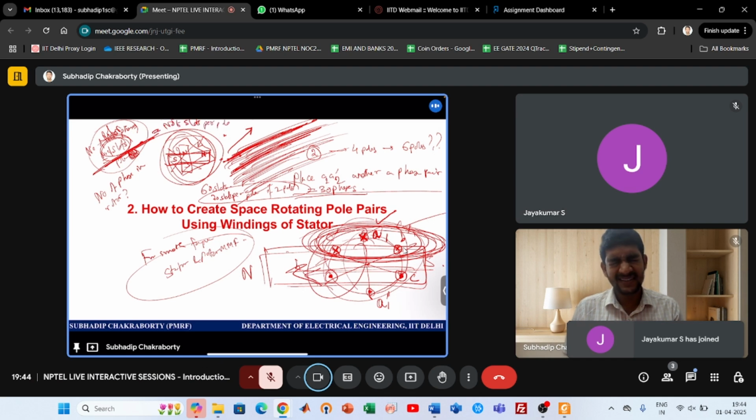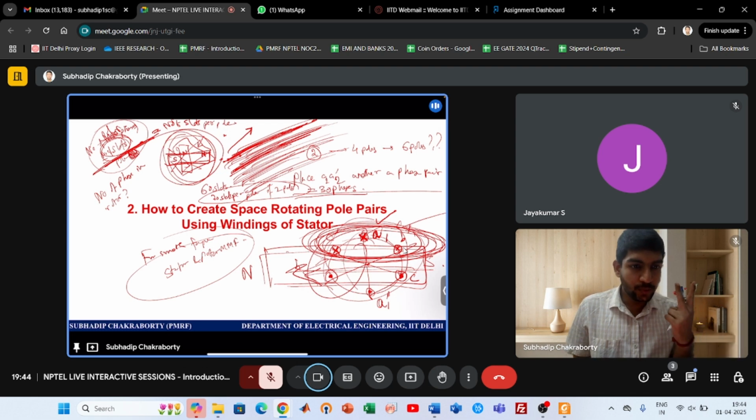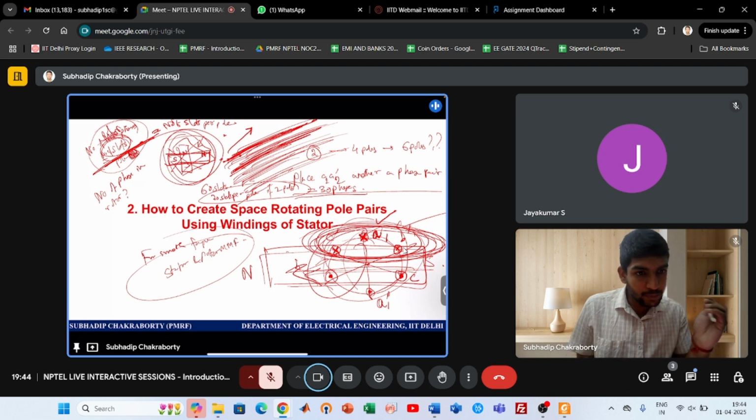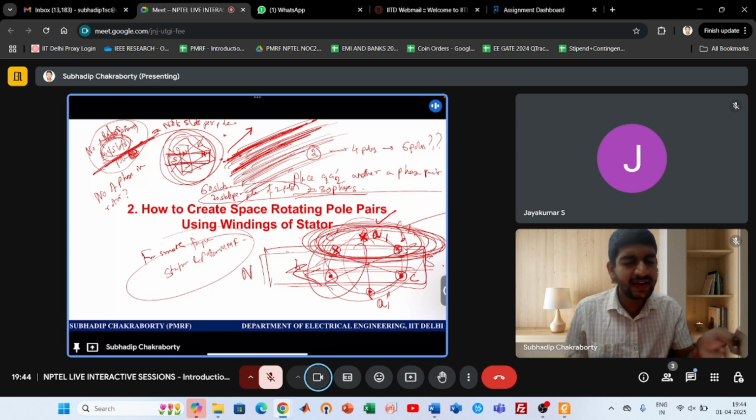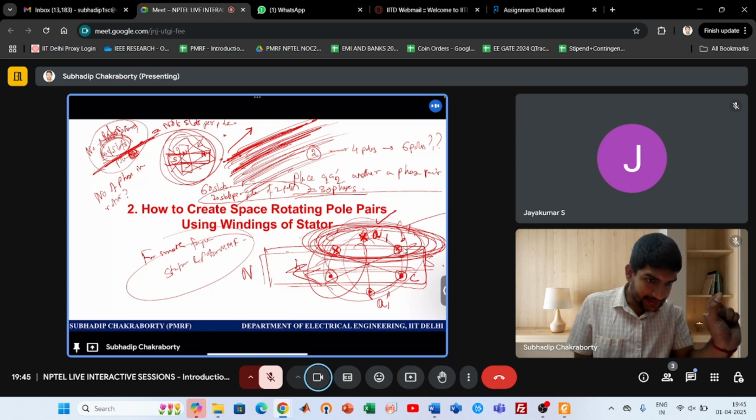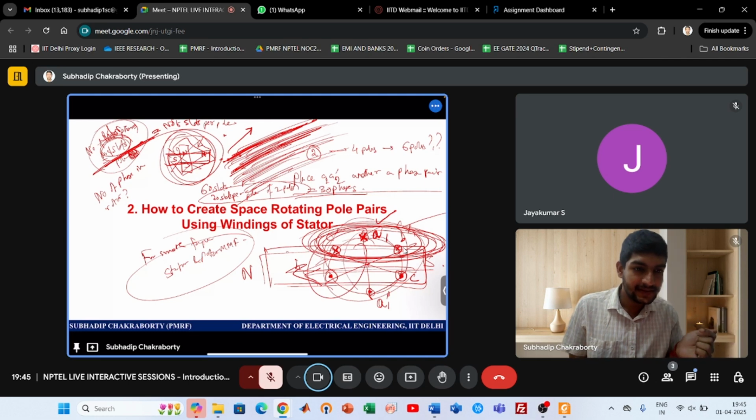So I told you what? That if the rotor has 60 slots and there are only 2 poles in the stator, the rotor will also induce 2 poles. Now per pole how many slots are coming? Per pole 30 slots are coming. So 30 phases will be there for the rotor. The rotor conductors will be 30 phase. Can you imagine? For a 3-phase system, there will be 30 phases in the rotor. So the number of poles should be equal, not the number of phases. My concept is clear, right?